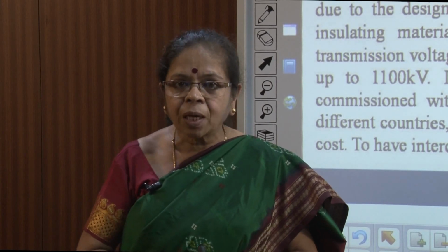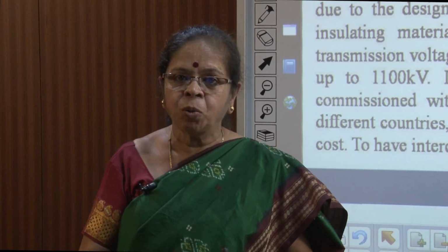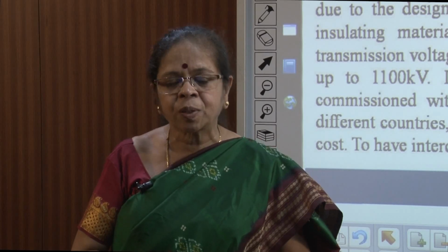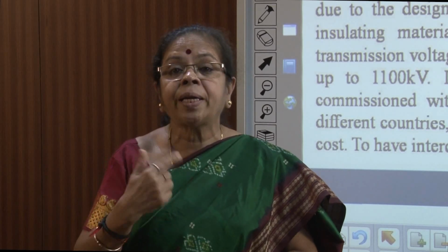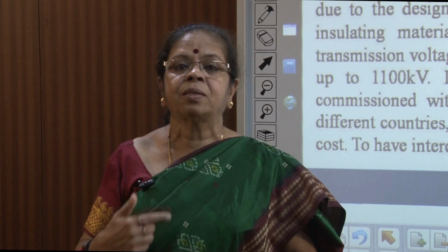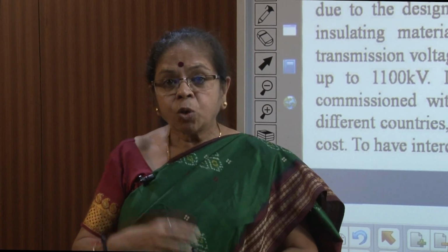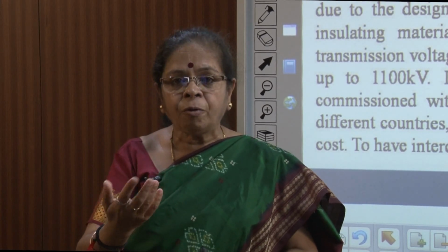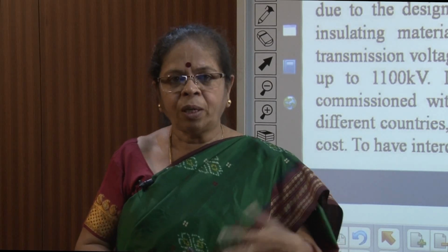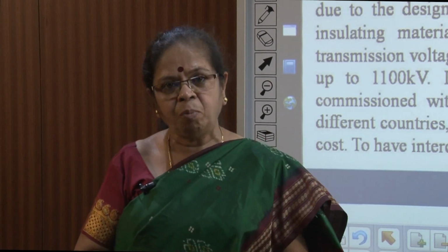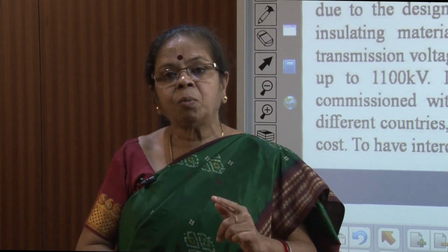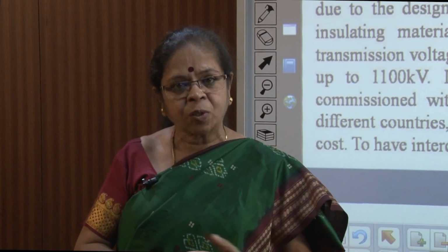The voltage drop is I into Z. So, if I reduces, the voltage drop will also reduce. So, now you can see why I kept harping about higher voltages. So, with DC, I do not have a way of stepping up the voltage. Whatever voltage I generate, I have to use the same voltage. That is the reason why DC systems resulted in heavy losses.